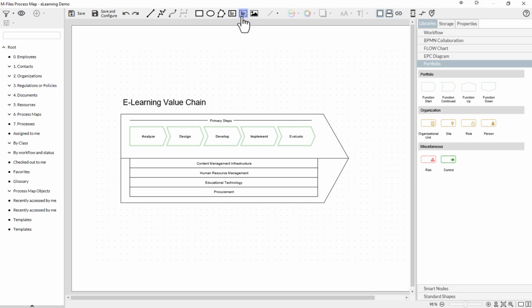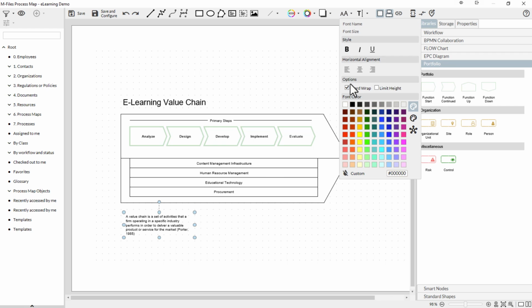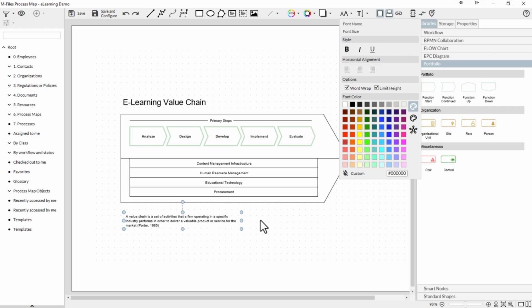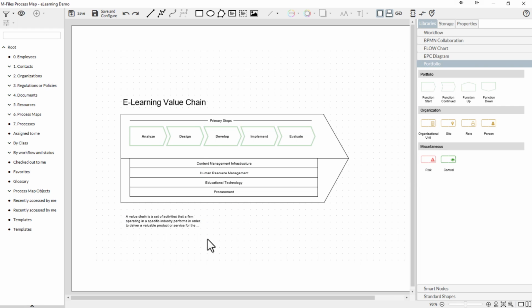The blue ports can be used to change the size of a text object so that the content fits better through a text wrap. You can use the Wordwrap or Limit Height functionality to adjust your text box to the format of a shape. Please make sure to toggle these options if you want to fit in large texts to small shapes. When you create a new text object, the option Wordwrap is switched on by default, so that the text will be adjusted to the width of the frame. If you also set the option Limit Height, then the text will be truncated so that it fits to the shape of the frame.